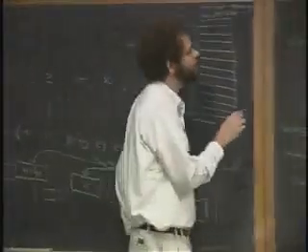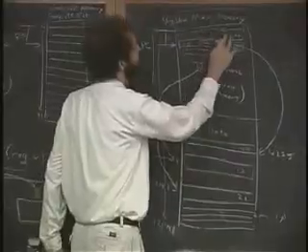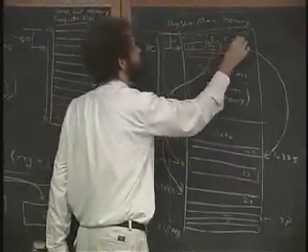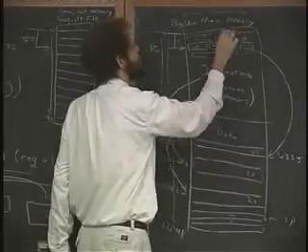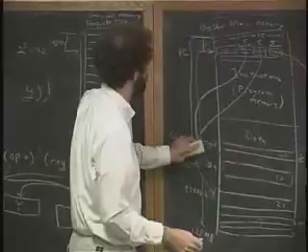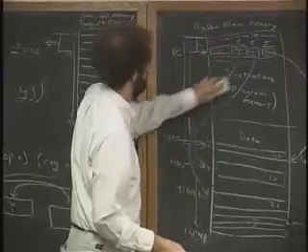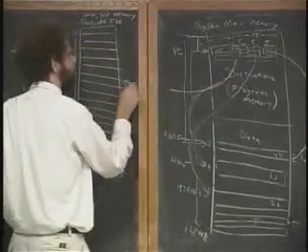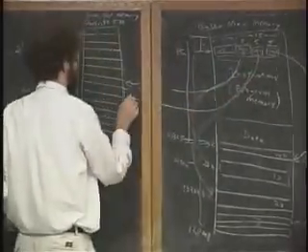And that means that our instruction word no longer needs 32 bits for each of these fields, but now can have just 5. And it's only 15 bits long. And these no longer point into here because they're forbidden from doing that, because they're not long enough to do that. But instead, they're going to point into different locations in the fast memory.